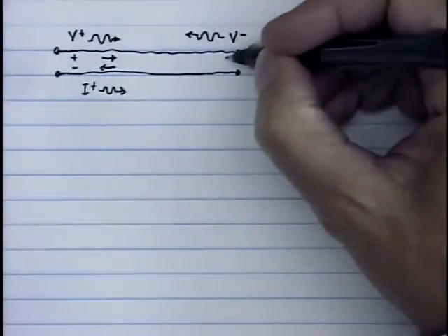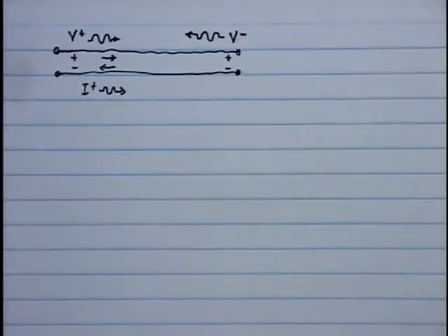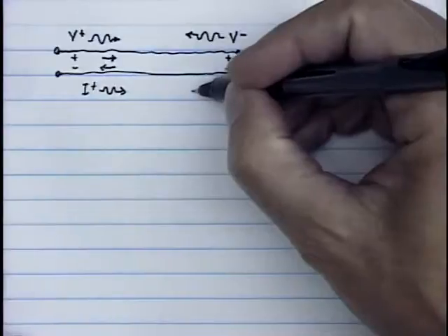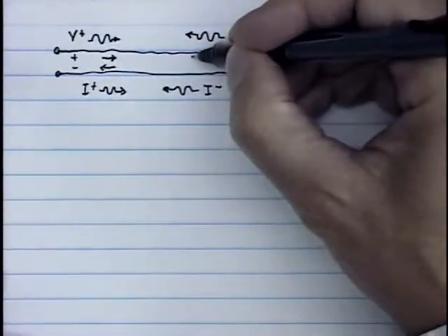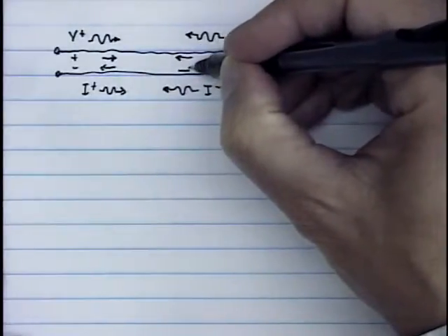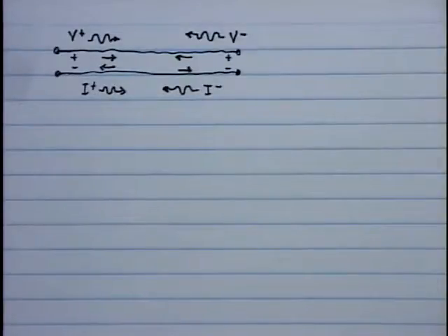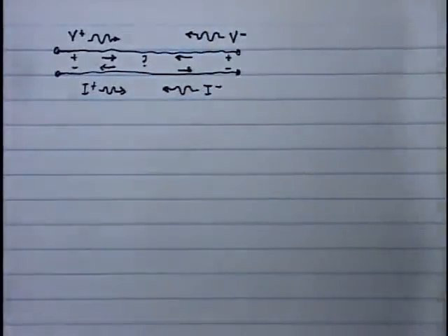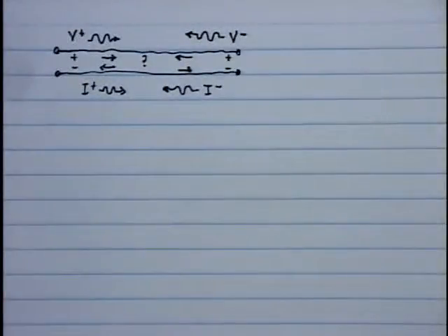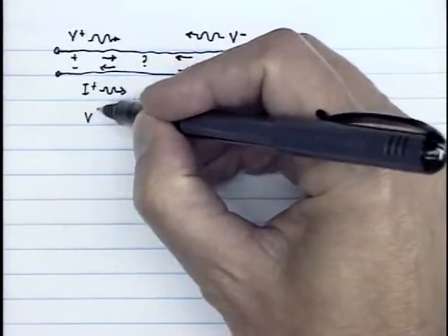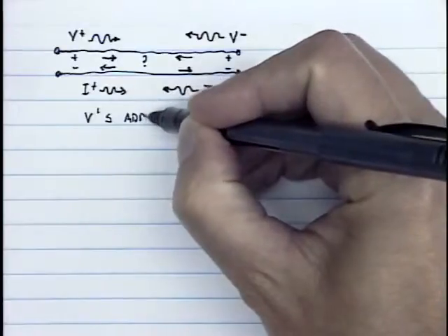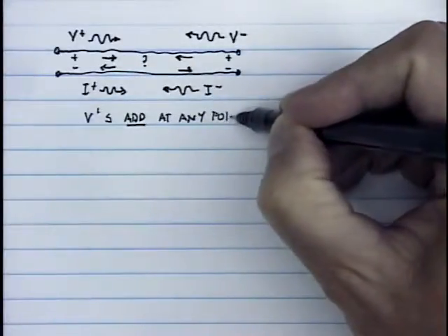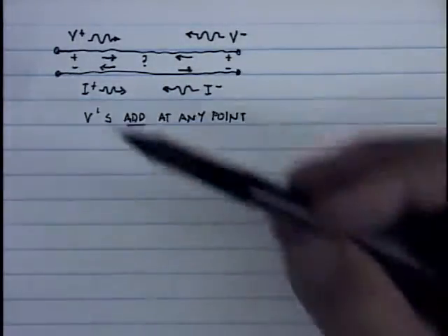And the polarity I'm going to use is the polarity shown here. And let's think about a backward traveling current wave. And once again, upper conductor has current flowing in the direction of propagation. The lower conductor has the return current. Those 2 waves are moving in from either end of the transmission line. Well, check out the polarities of the voltages. They're the same.